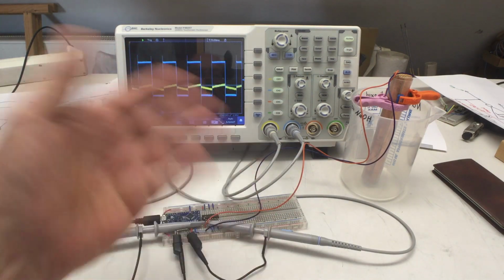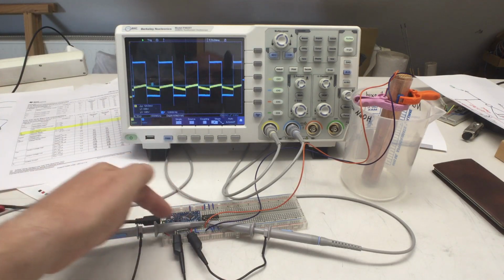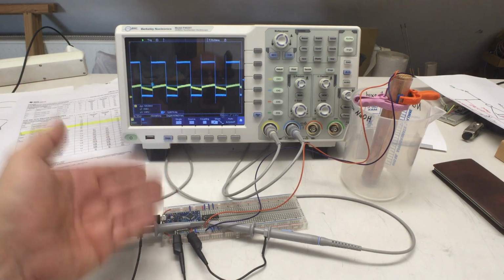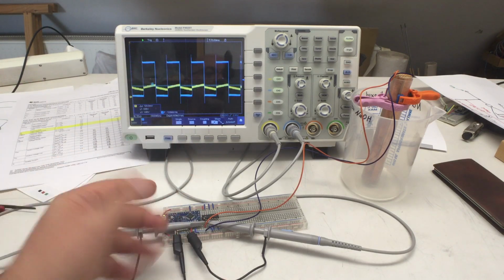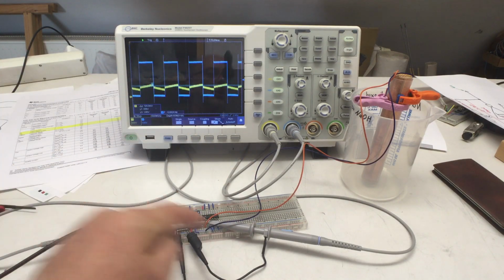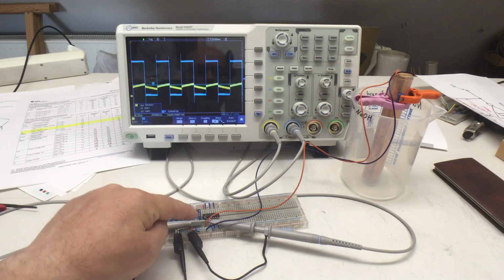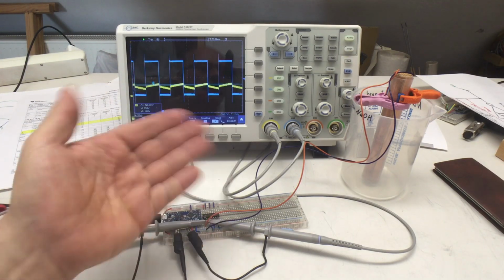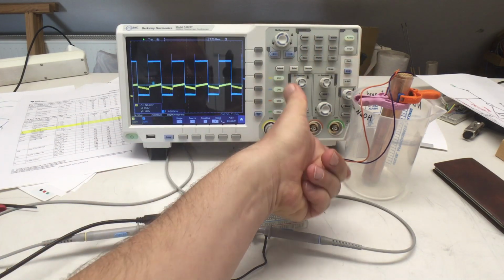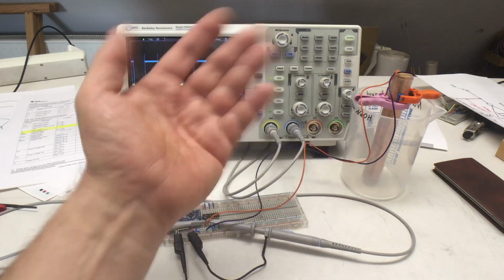In this video, we will actually go digital and measure the capacity with an MCU. That is, in this case, an Arduino Nano Every. That is, we are going from analog to digital. I already got a working RC oscillator here that we built in the previous video, which changes its frequency with the capacitance of our sensor, that is, the fill level in our container.